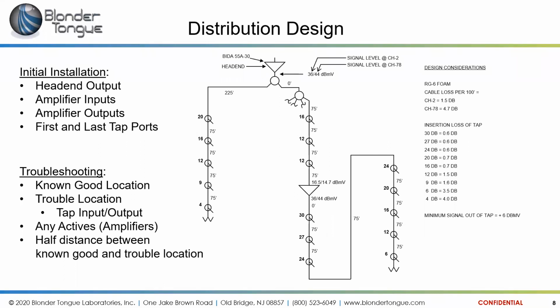In a 550 megahertz system, I've had issues with channel loss, which fall in the 200 to 300 megahertz area. Not sure if this is called a suck out. So my low and high channels are fine, but there is loss in between. What are the usual culprits for this sort of thing?